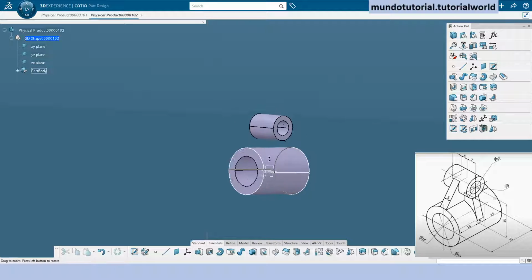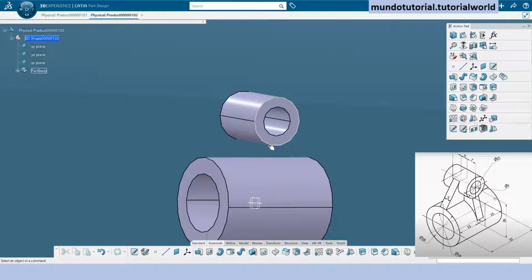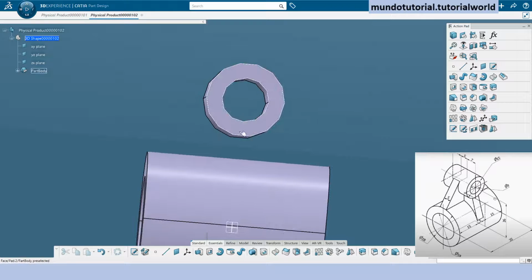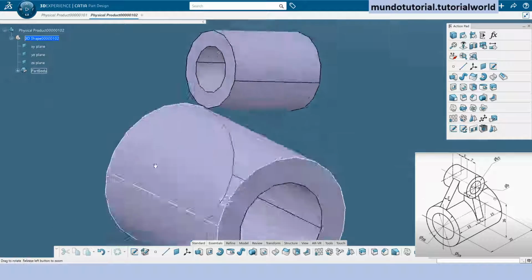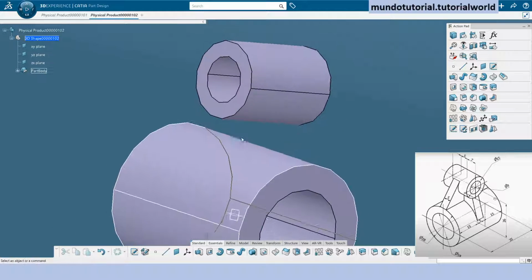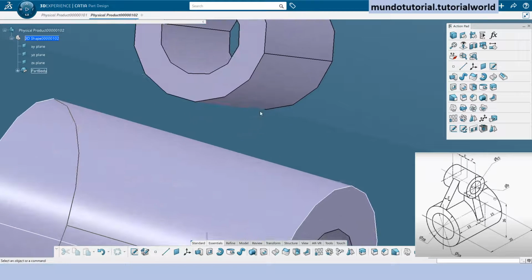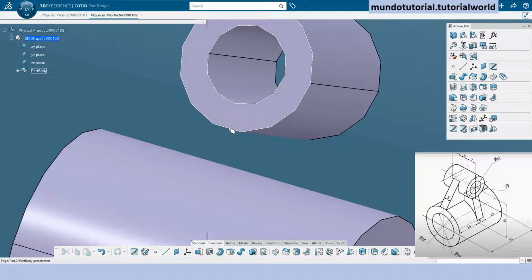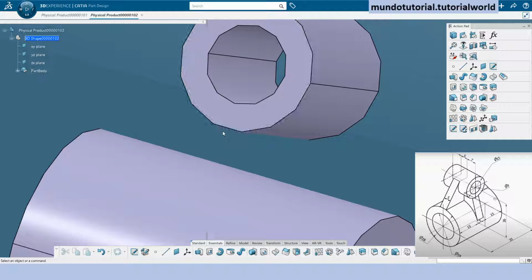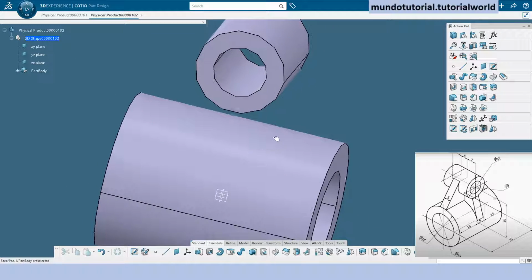So in this area, if I try to do a sketch from this view and try to do the path in that direction, I will lose material, because imagine that if you have a point here going in that direction, it will go straight. And as this is with a curvature, you will not be able to fill this material.